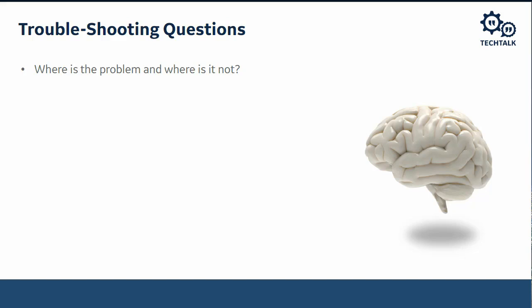The next question I would typically ask is, what is unique about that motor? If I'm looking at those 5 motors and the one motor that's tripping has recently been rewound, that would be something unique, and something I would want to zero in on as I try to figure out what was going on. Another question is, when did the problem start? Using the same example, if the problem started immediately after we had it rewound, that would make me even more suspicious that something happened during the rewinding of that motor.